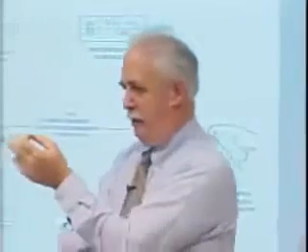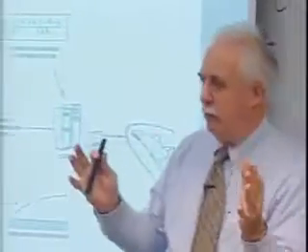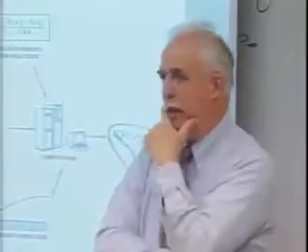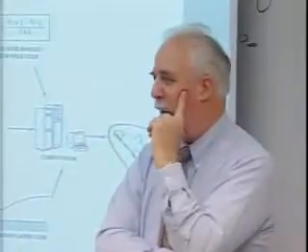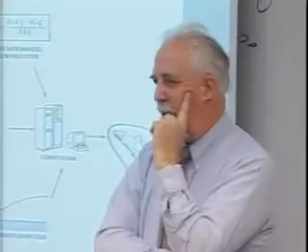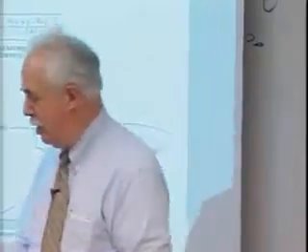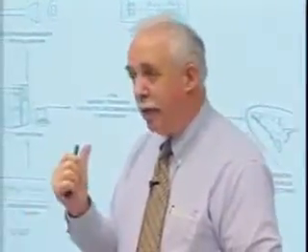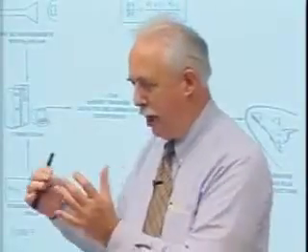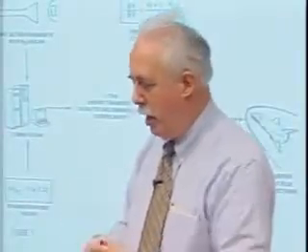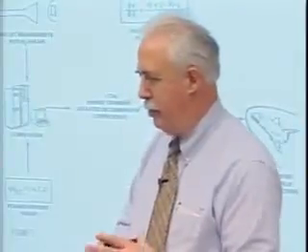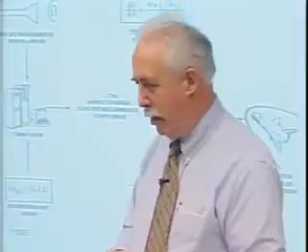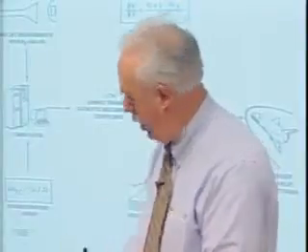The tiles are a very efficient system. They're low weight, they're fragile, but they're very efficient from an energy standpoint. The carbon nose and leading edge are heavy, and they don't insulate worth a darn. That's a layer of carbon. When it gets hot, it radiates out, but it also radiates in. And so you have to have an insulation behind that. And in fact, the way we were able to reconcile the environment with the temperature capability of the carbon is sort of like an oven, and it's easier to illustrate on a leading edge.